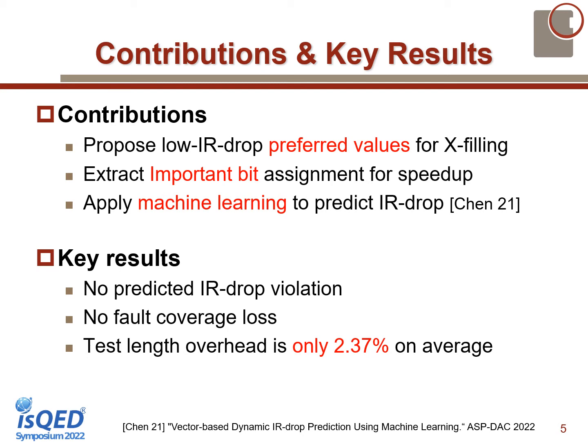Our results shows that we achieved the goal of IR drop safe pattern generation. There are no predicted IR drop violation in our output test pattern set. There is also no fault coverage loss and only slight test length overhead at 2.37%.